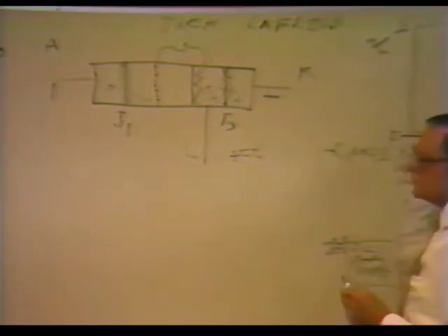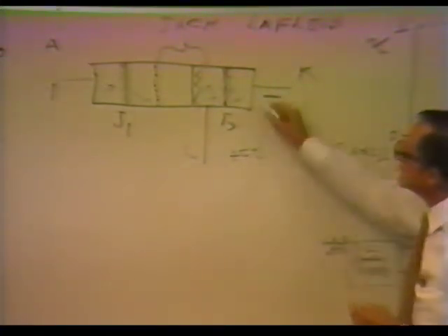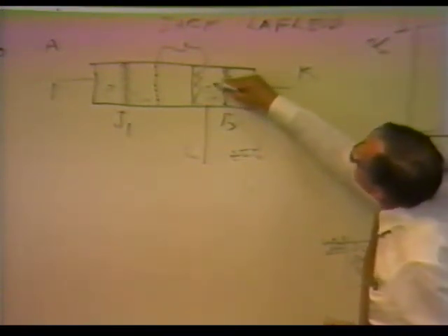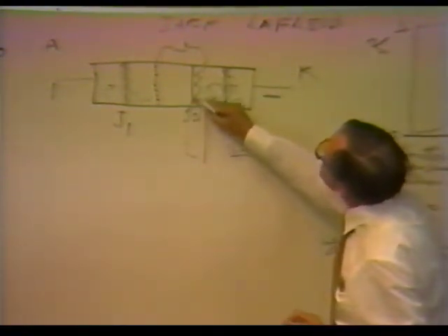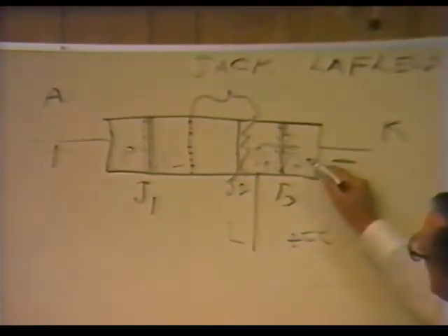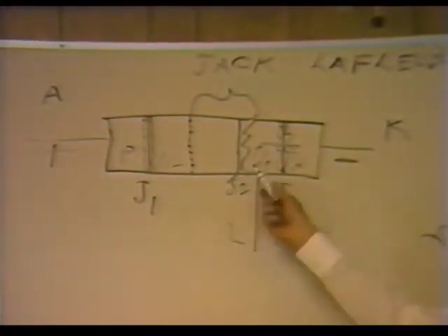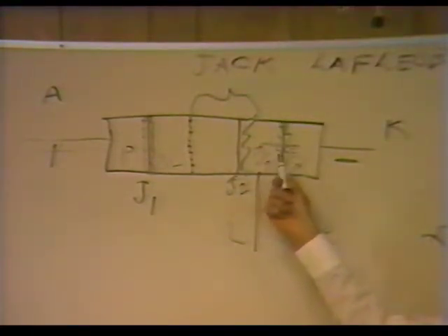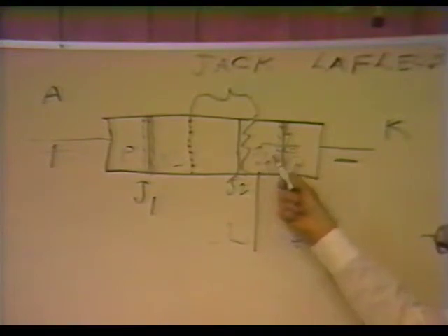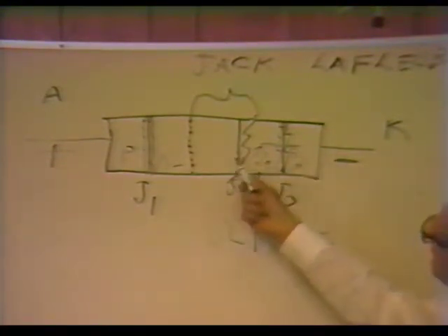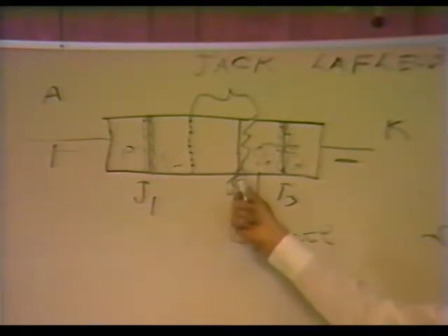The emitter starts to emit carriers, electrons, and they go across the junction and are collected here at junction J2. You've got N-type carriers that pass through the P region and are collected here. Some of them recombine, we lose some of them, but this unbalanced junction now gives them enough mobility to go over and be collected at junction J2.